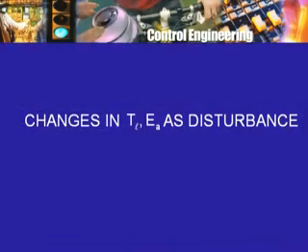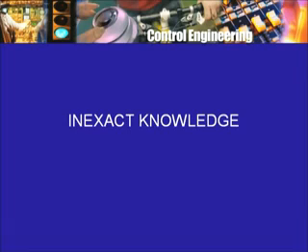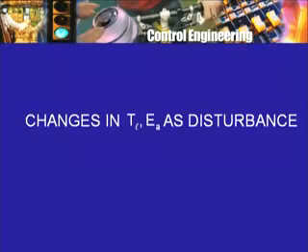Similarly, TL, the whole purpose of the drive is to drive the load which is going to demand a load torque. So, TL is not a disturbance in that sense, but what can be considered as a disturbance is the possibility that TL is not known or TL is not at the value for which the calculations were made. So, in this sense EA and TL could be looked upon as disturbances, or rather changes in them or lack of exact knowledge about them could be thought of as disturbances. And of course, as far as the supply voltage EA is concerned, one can find reasons for changes in EA. For example, the same power supply is also supplying some other device which is getting switched on or switched off, as a result of which EA can change if the power system is not properly designed.